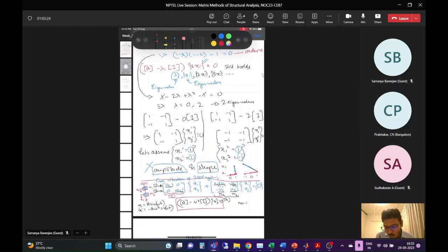Why mode shapes? Because the amplitude doesn't have any significance. How do you correlate that with a physical thing? For a different vibration, how that mass is vibrating, basically, is the mode shape. Now I would try to make you understand the physical significance of it.